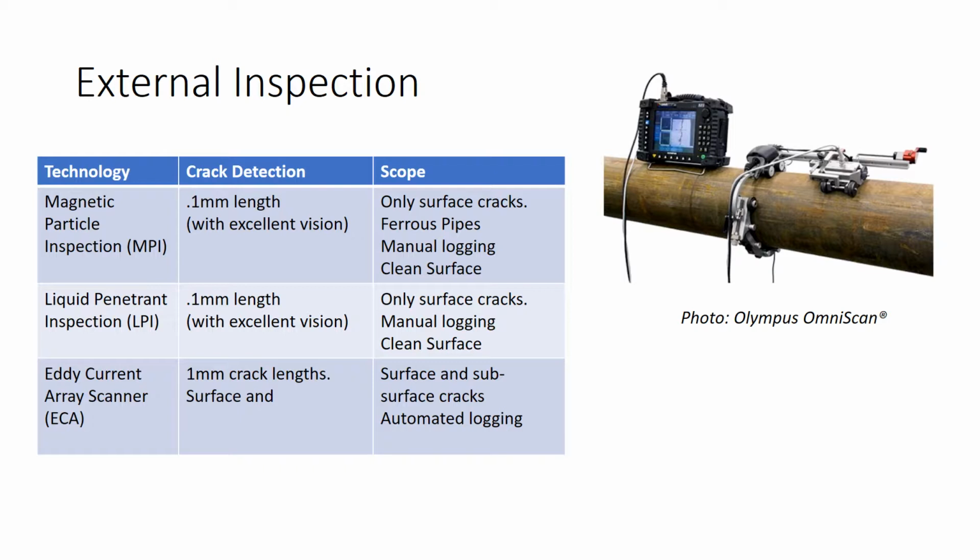Magnetic particle inspection, known as MPI, enhances the visual contrast between cracks and their surroundings. A solution containing tiny ferrous particles is applied over the area to be inspected. A strong electromagnet is passed by to temporarily magnetize the pipe, which causes ferrous particles to get stuck in the cracks, thereby making them easier to see under blacklights. MPI will not work on stainless steel, titanium, or Inconel.